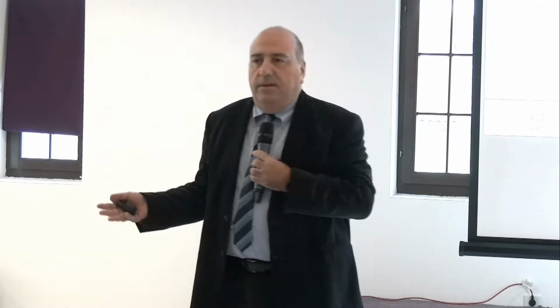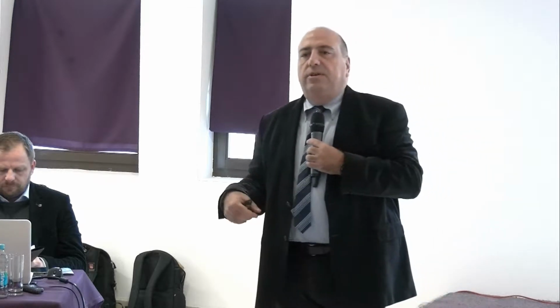Why? Because if you forget one valve that is not captured, all the zoning is wrong. You understand the problem? There is a pipe linking 2 zones that you didn't see and you didn't record, and all your network is wrong. So the issue is serious. The final objective of phase 1 is for everything to be in, not 98, 100%.